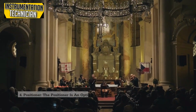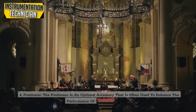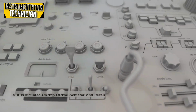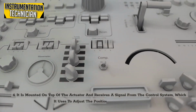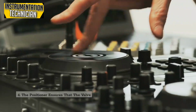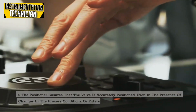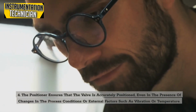4. Positioner. The positioner is an optional accessory that is often used to enhance the performance of the control valve. It is mounted on top of the actuator and receives a signal from the control system, which it uses to adjust the position of the valve plug. The positioner ensures that the valve is accurately positioned, even in the presence of changes in the process conditions or external factors such as vibration or temperature.